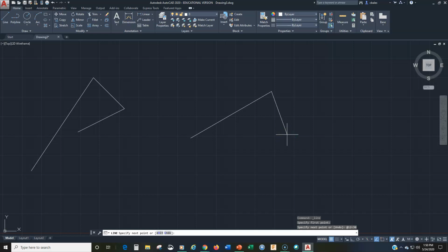Okay, so I would say that line that I have drawn is about 6 units long. Okay, @6 is the distance, angle symbol. Now, what angle is that going to be? Well, if we look at due east, moving in a counterclockwise direction, we're actually coming all the way around from due east through north, west, and then coming down to south, and then another 30 degrees, it looks like, from south.